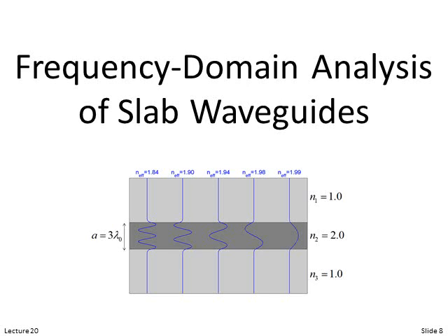Now the ray tracing is good for a quick, fast, sort of qualitative understanding. We need to get much more rigorous about this. We need to analyze our slab waveguide rigorously because our source in finite difference time domain needs to be pretty darn close to a rigorous solution. So we'll calculate these modes, and then given that, we can excite any combination of those modes that we want